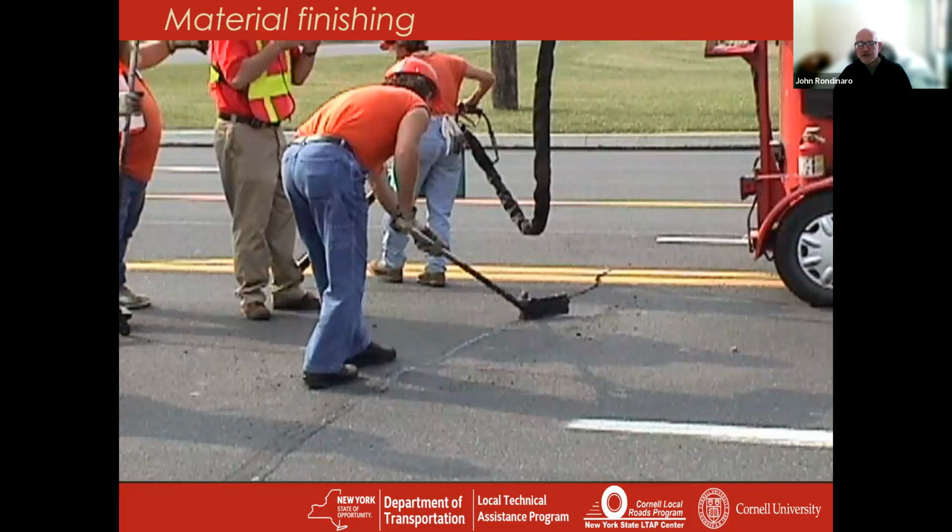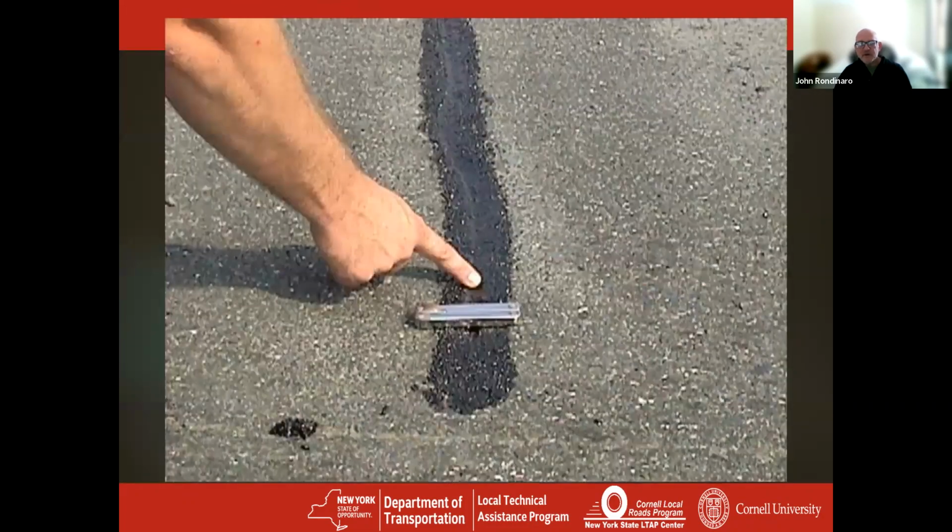And in terms of finishing, it's as simple as getting a squeegee from Home Depot, putting an inverted V on the end, and then running the bottom of the V across the newly placed material, and it'll leave a surface that looks just like this, with a nice little indentation. You don't want to be overfilling, because when that crack is tightening up as the temperature gets lower and lower, you don't want to be pushing that material out above the existing surface of the pavement. Otherwise, it becomes a target for your snowplows.